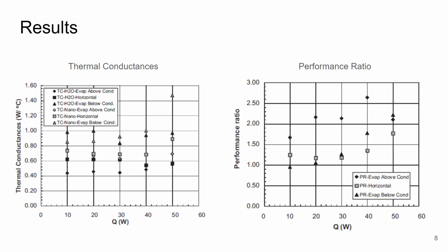And based on performance ratio, we got at low heat loads for the nanofluids, the temperature difference for the adiabatic and evaporation sections were smaller than for the higher heat load sections. From this, we could say in the lower heat loads, film evaporation effects were more predominant than nucleation boiling. We believe since the increase of the copper nano, we had the increase of the thermal conductivity, which had a direct affiliation with the film, and this film affected the pulsation flow. But as heat increased, we noticed that nucleation boiling takes over.